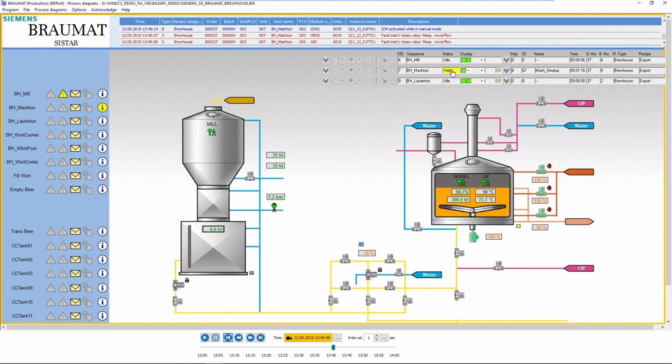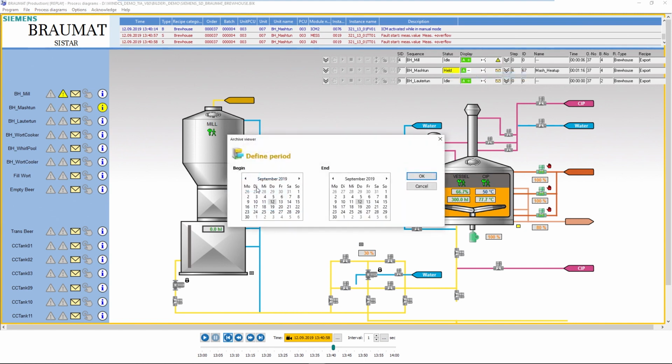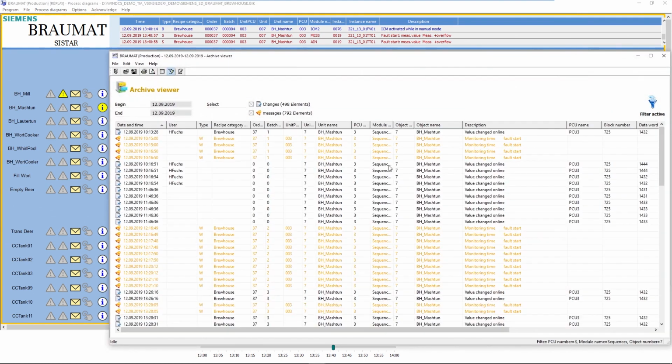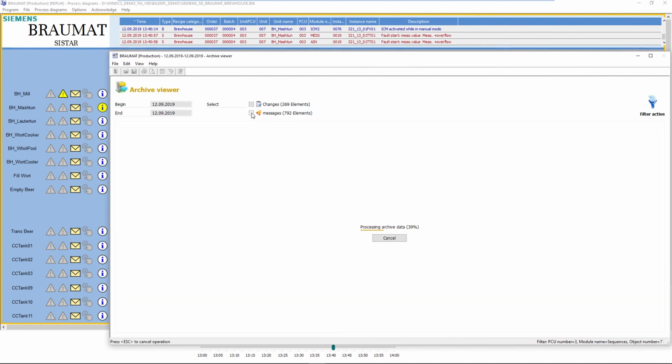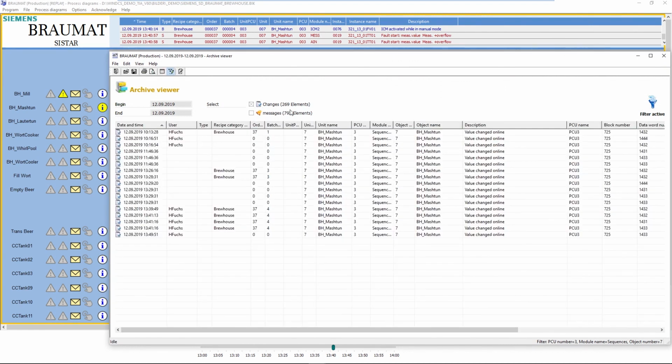Hold is a scenario that the automatic can provoke via a so-called exception handling. But this could also have happened if set by an operator manually. How do I now find out which of the two scenarios is the case? Again, I can use the context menu to look into the past. This time it is not the messages that are relevant for me, but the so-called changelog entries.